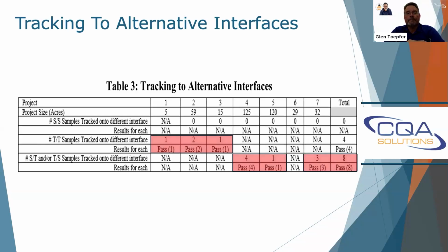And kind of another note on that, we were working on a cap, maybe a year or two later, and they're doing the 40 mil LL, and you have a lot of butt seams on the cap, and they do the 45, and you have your textured interface. And I brought this up to the engineer. I said, we're failing on these butt seams. Should we evaluate more? Increase our sampling, make sure we increase that.